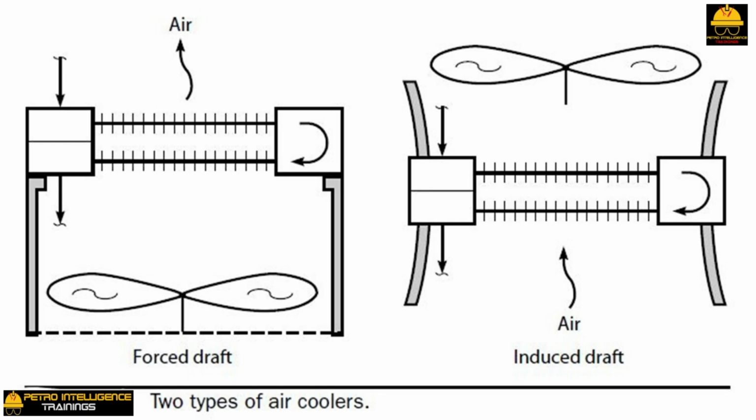The heat transfer coefficient of an air cooler, that is BTU per hour per square foot of fin area, per degree Fahrenheit, is not particularly good. It might be 3 to 4 for cooling a viscous liquid, or 10 to 12 for condensing a clean vapor. The low heat transfer coefficients are offset by the large extended surface area.